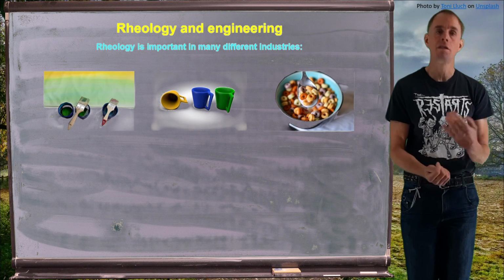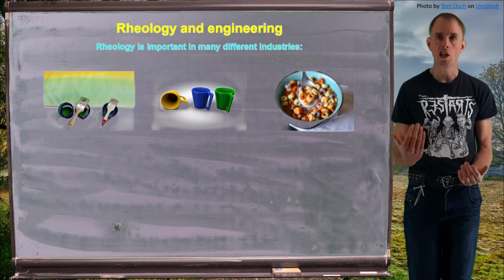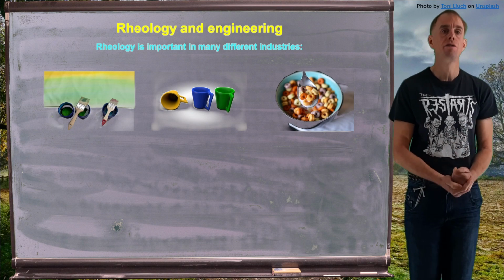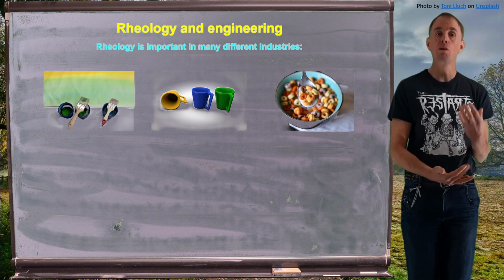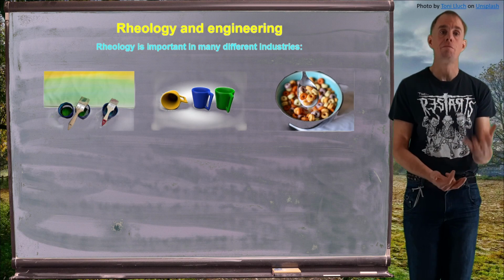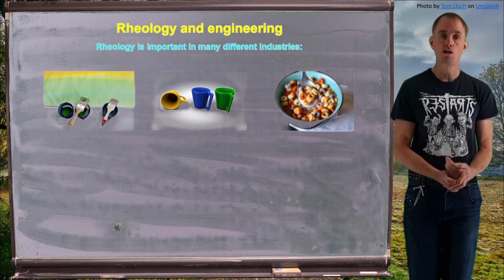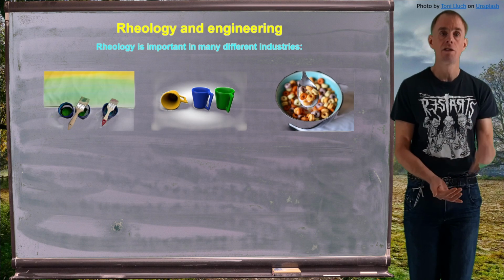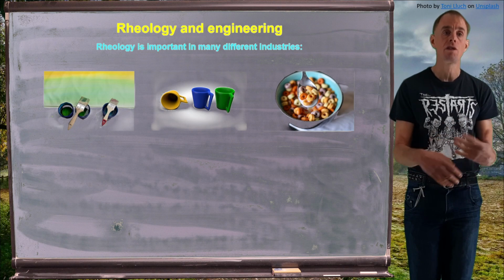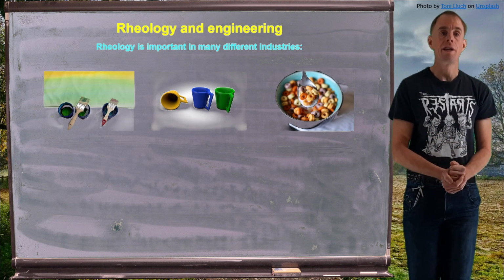It might be a starch melt, it might be a starch solution that we wish to shape form. Extrusion is a very good method of shape forming, and so we'll extrude this starch melt or these starch solutions or starch derivatives through a set of extrusion dies that'll then go through cutters and then goes through some process to ensure that that shape is retained.